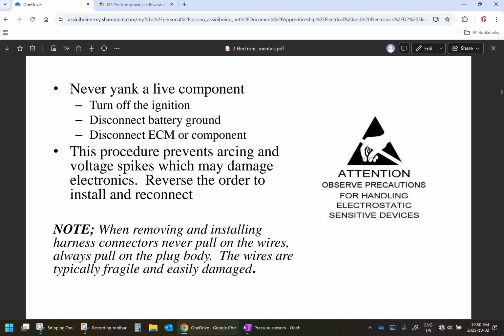Okay, so let's say that we do have a circuit, and this circuit has an intermittent fault. Like every once in a while, we set a code, but it's not always there. And it's because of a wire that's broken where you have those conductors touching inside the insulation every once in a while and disconnecting every once in a while. So what I would do in that case is try to force a code.